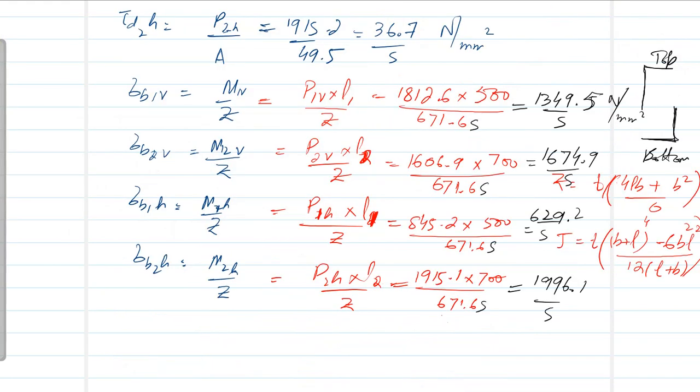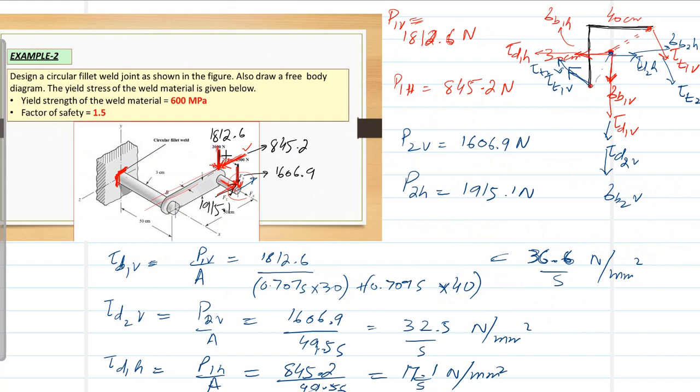Third case, we have to find all torsional shear stresses. So tau T1 is equal to T1 R1 over J, because the torsional shear is only produced by vertical components, so there is no torsional shear due to horizontal components. So we have only two torsional shears. I'm again repeating that the horizontal component is not able to rotate it. It can only cause direct shear or bending.